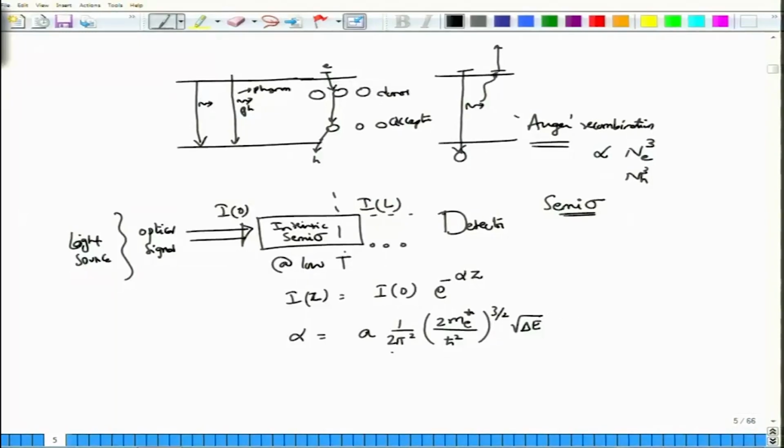Why this particular component here? Now what is this component? This of course is your energy, this of course is the density of state. So what we mean here is that if there are certain electrons available, then these electrons will absorb part of the optical signal and thereby get excited into the conduction band, right? And the availability of such electrons, or how many states are available for these electrons to absorb and therefore go into the conduction band, is governed by the density of state expression. And of course, it is also dependent on the intrinsic absorption property of the material, which manifests in the form of the complex permittivity of the material itself.